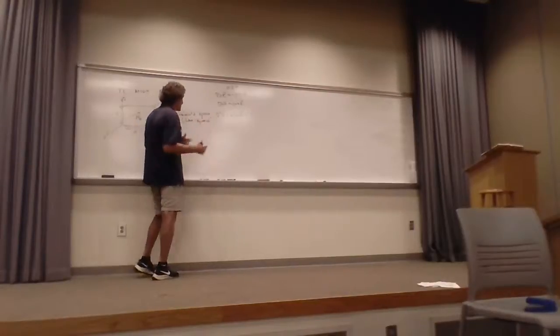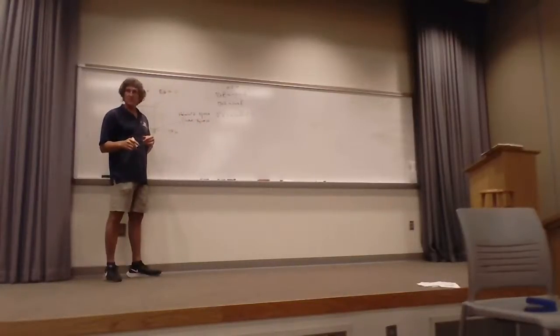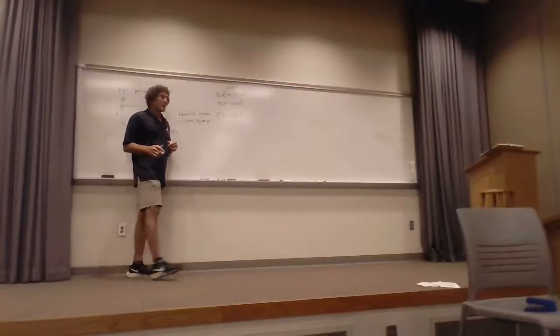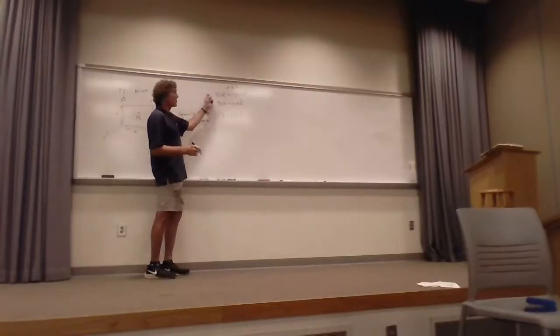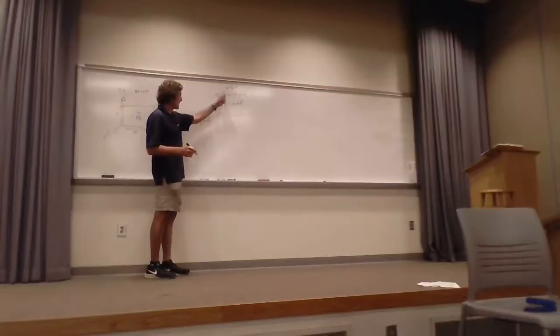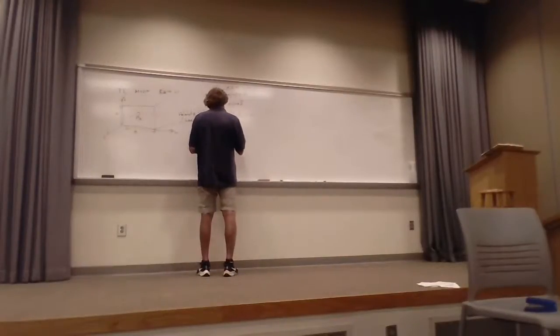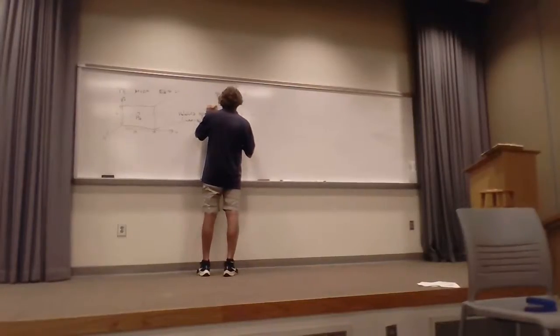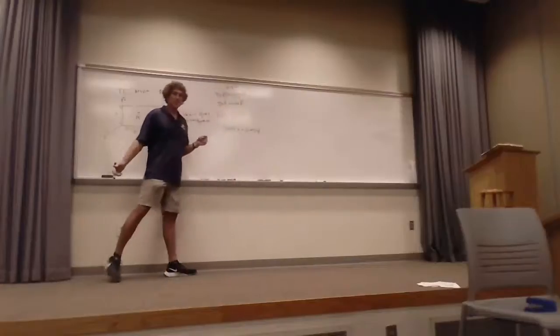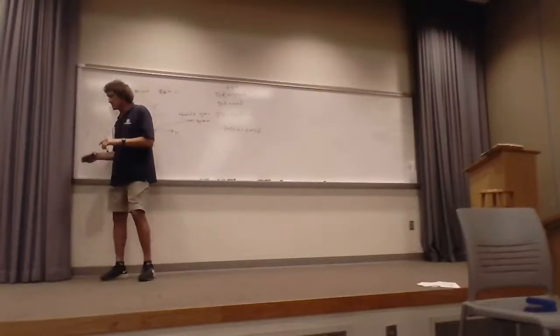It's a general wave equation. It's a lossless wave equation. You don't need to worry about that. If instead of taking curl of E and then substituting curl of H in here when we had curl of E, get a curl H over there. If we did it this way, if we took curl of H, you don't need to write this down, just appreciate what I'm doing. Curl of H is equal to j omega epsilon times curl of E, right? So what would I do next? I want one equation with just H.